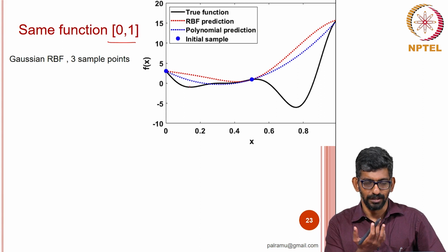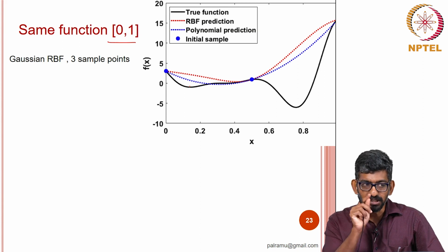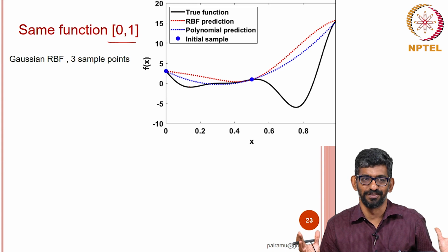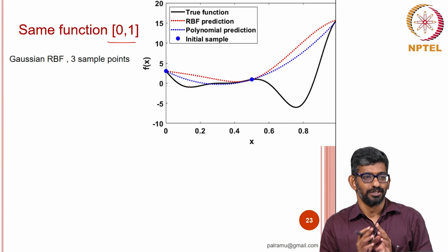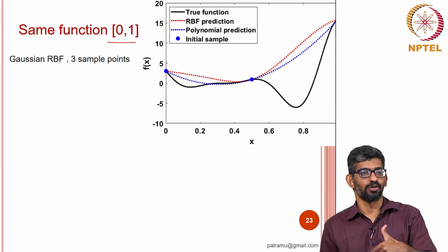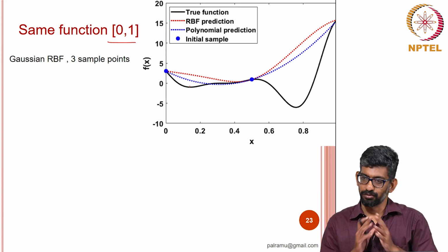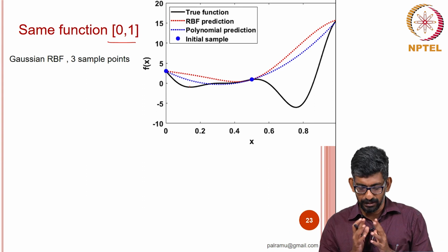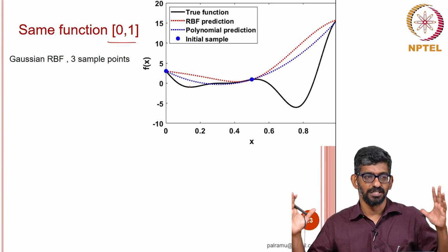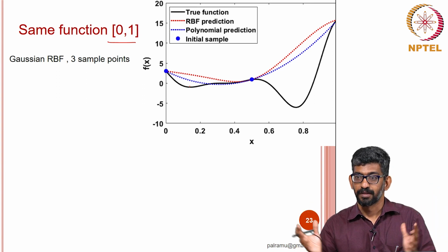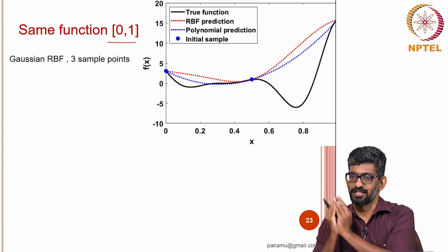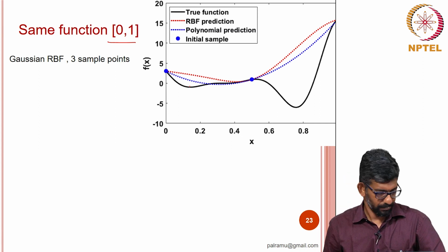So, it is an interesting point, because if I know this a priori, not throughout the same difference, then it will be good. That is why the PRESS error or the cross validation errors are more relevant than R squared. R squared gives you an idea about the entire design space, how good the meta model is in a global sense. But PRESS error gives you the local picture, what the errors are with respect to the local basins.